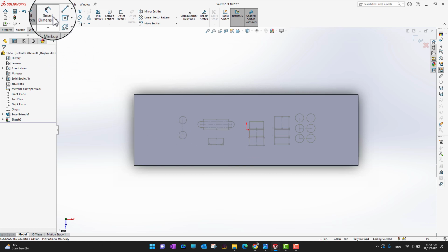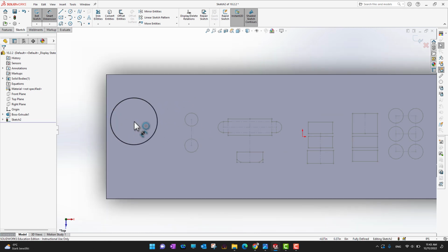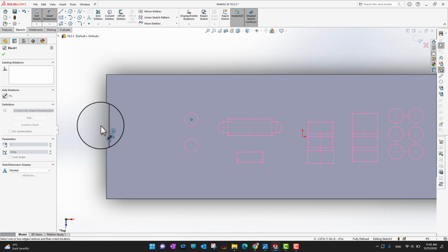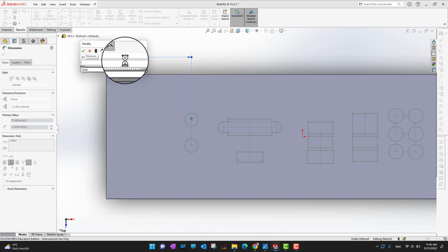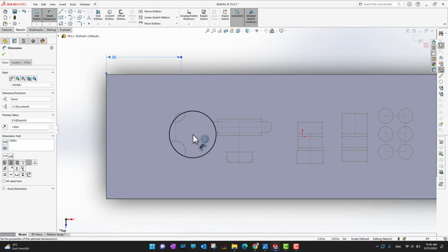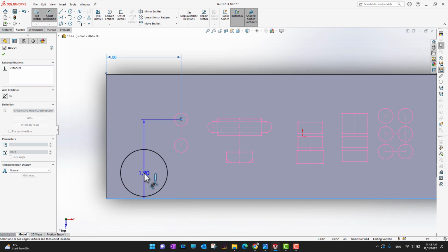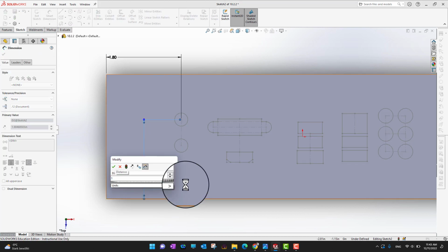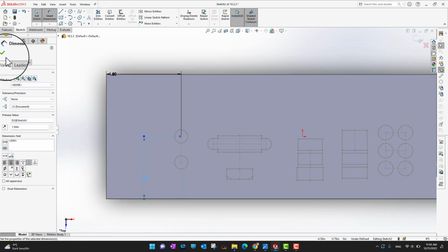There is another thing: I would like to have some dimensions. If there is some specific distance I want from the side, say I want 1.8, I'm just going to select 1.8. And if you want to set the height as well, I would say I want to insert it at 1.5 inches high like that. And when you are done, you can just click the green check mark.